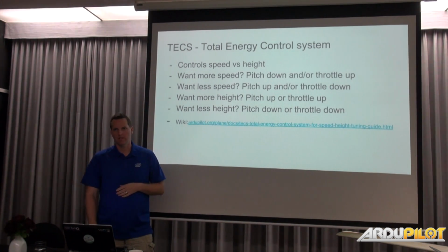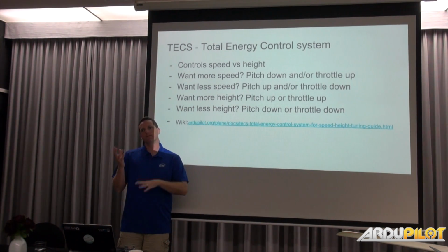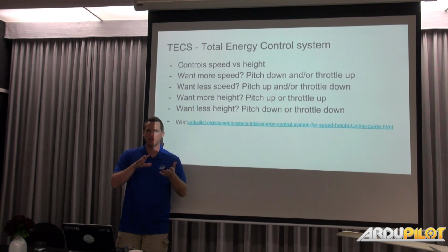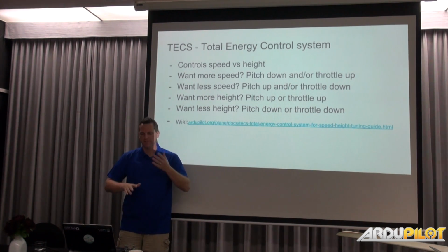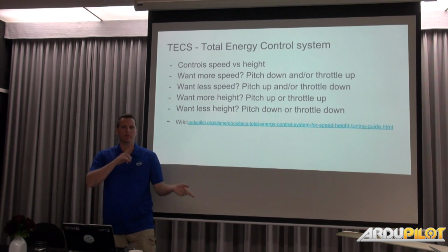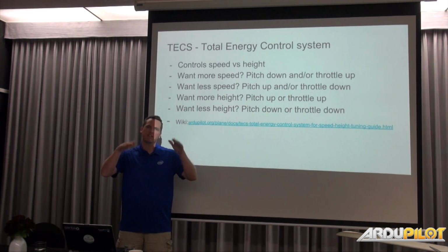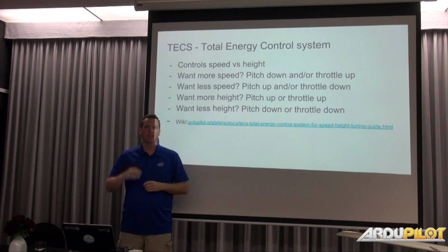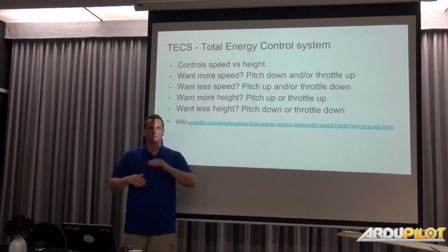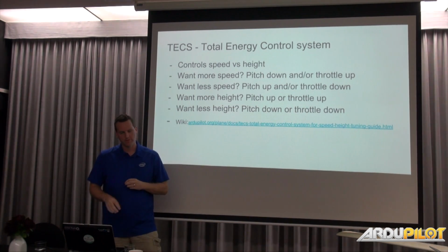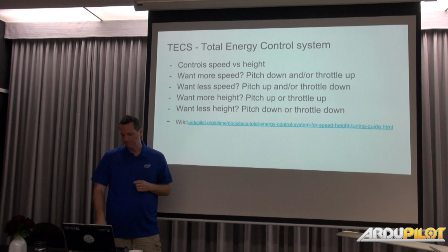The TECS controller is basically always figuring out this big mixture of energy: if you put energy into it, then you keep going, and if you take energy out of it, you're going to drop. So there's always this balance to it. More speed, you pitch up, and vice versa. During flight, it's not a big deal because usually you're keeping the same altitude, so you fix your altitude and then add throttle for a little bit. But on landing, all that's adjusting, so you want to tune this a bit to make it work well.